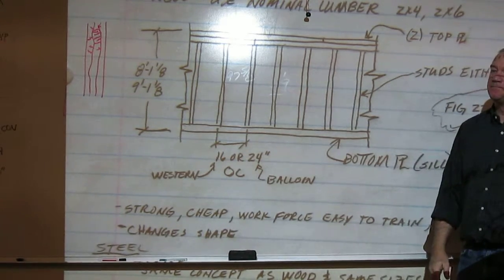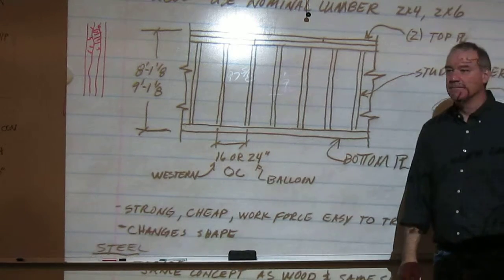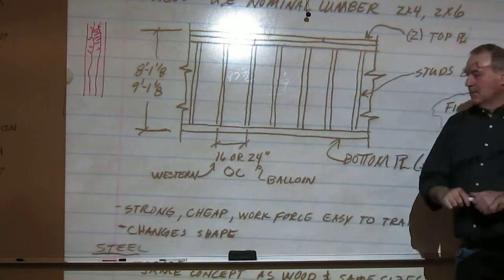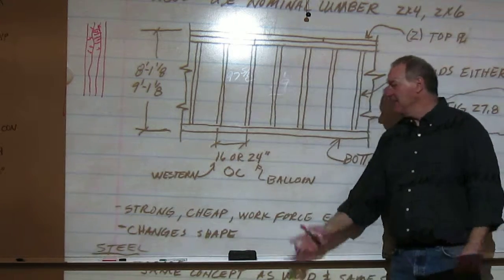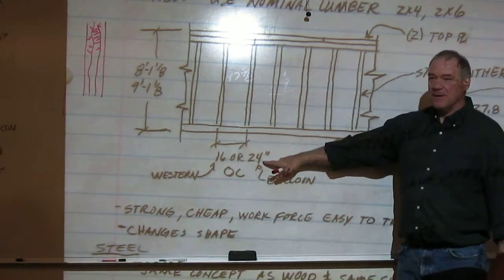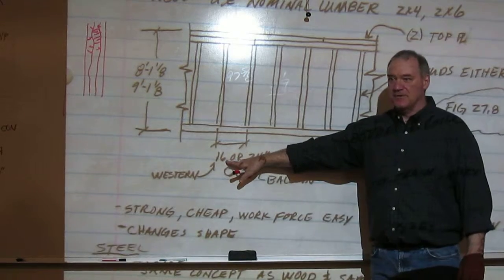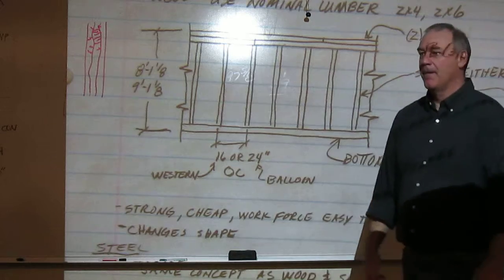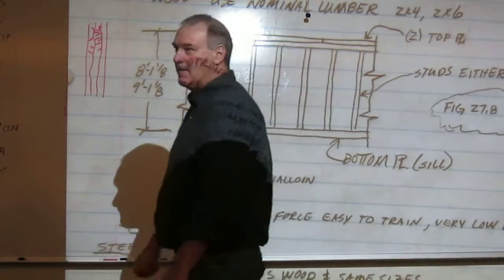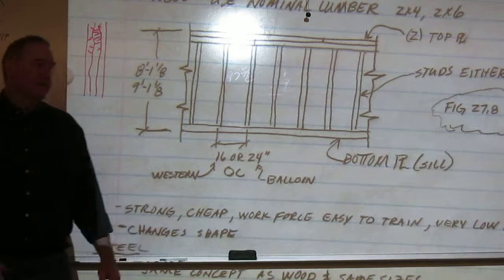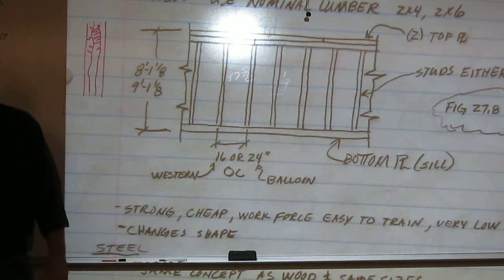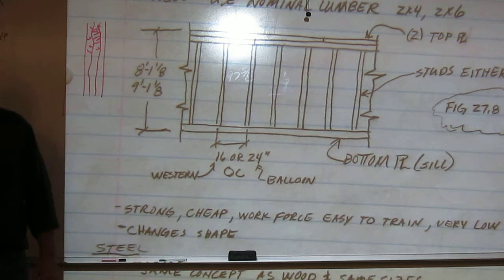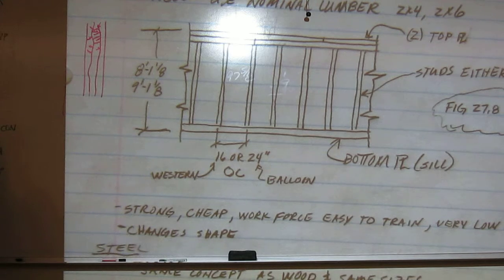If you're really watching your budget, would it be cheaper to go 24? It is quite a bit cheaper, because you have to figure in every 4 feet. One layout requires 2 studs, the other requires 3. So every 4 feet, you're saving the cost of one board. You could run it out, that's approximately 1/3 of the cost. Which is how some production builders get away with things sometimes. A lot of times they'll frame an entire house on 24s and 4-inch walls instead of 6.